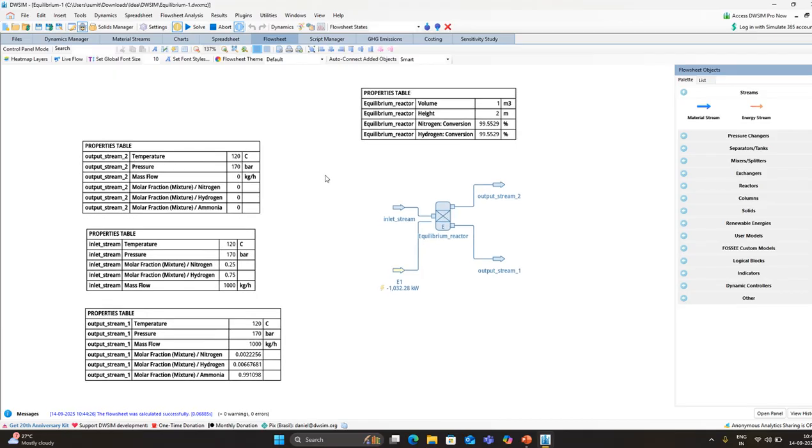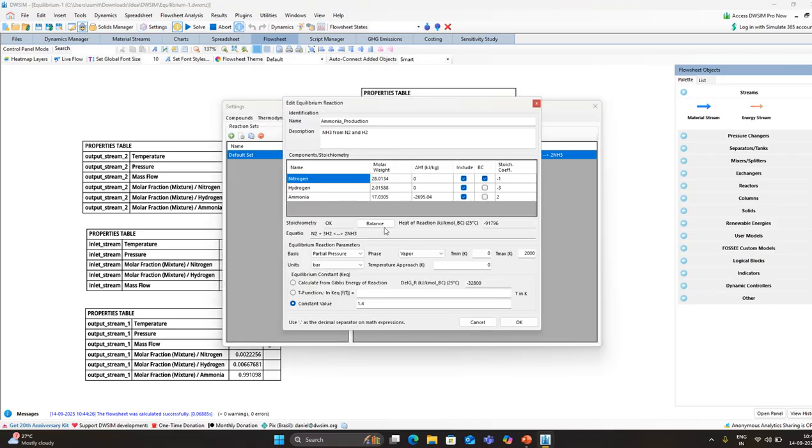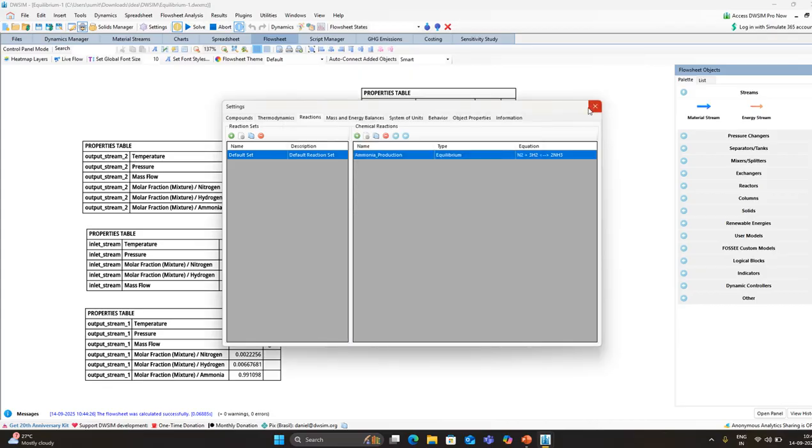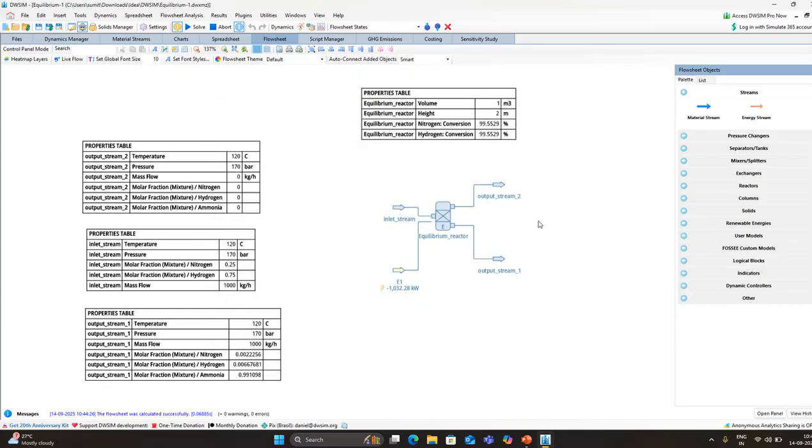So I just need to optimize the temperature. I should always optimize for the temperature, linking the temperature and the reaction constant. This is also available. You can see here we can introduce K as a function of temperature. Then I will just increase the temperature in my sensitivity analysis and find at which temperature I get the highest production. That will be the ideal case scenario, but this data is not available with us right now.